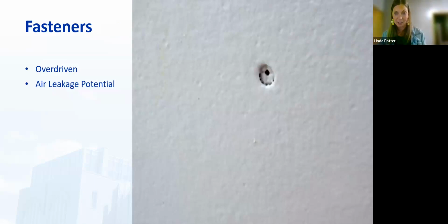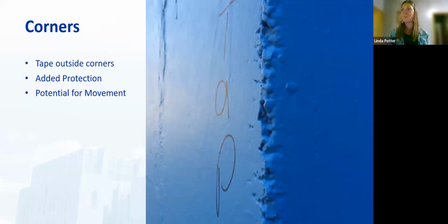Some kind of detailing material. And usually we're going to detail first. Now, that's not always the case. You're going to look at the manufacturer's installation instructions to know what mil thickness and what product goes on, and whether they detail first or after. That's going to be specific to the product, but you're going to want to make sure the contractor knows when and what they're using to detail, and that they understand we're not just going to spray over that and leave it.